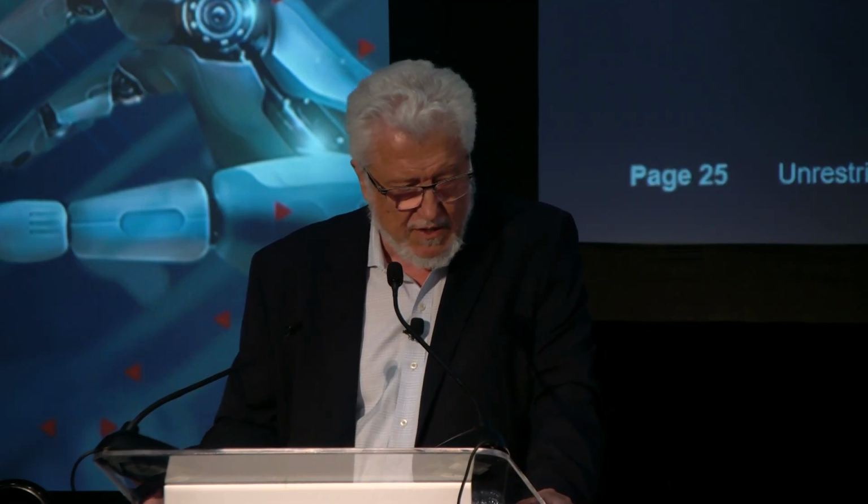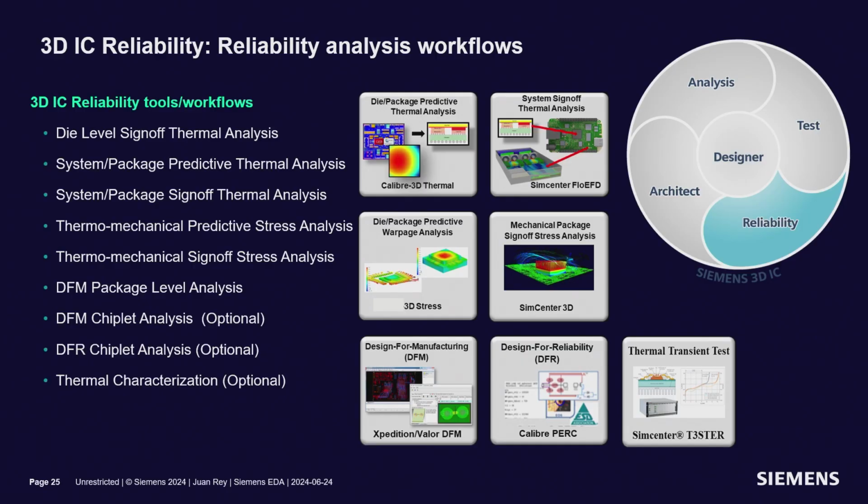So I will be focusing on only one of those flows as an example. What you see on the four insets in the center is that one of the critical areas the whole industry needs to pay attention to is thermal dissipation, given that the heat generation comes from the electrical characteristics of the system, both by switching devices as well as due to Joule heating.